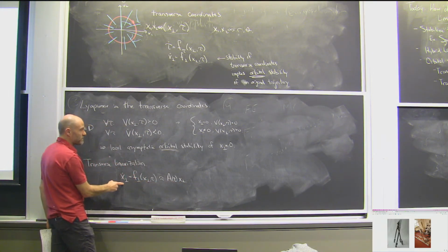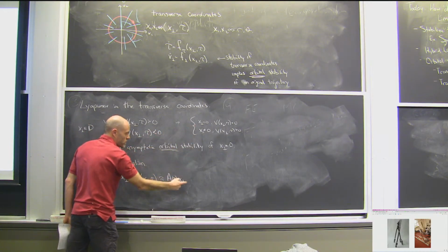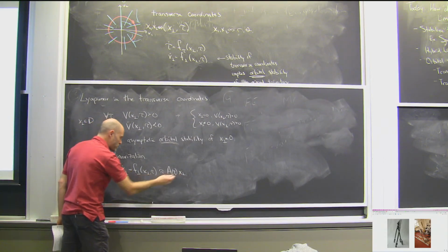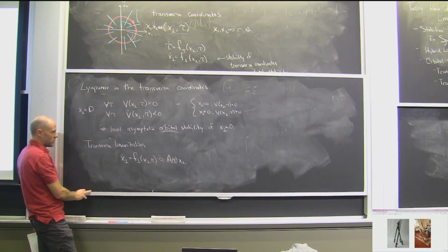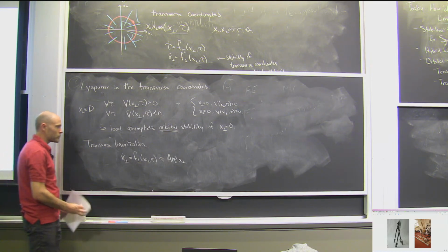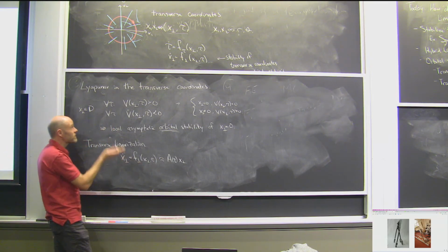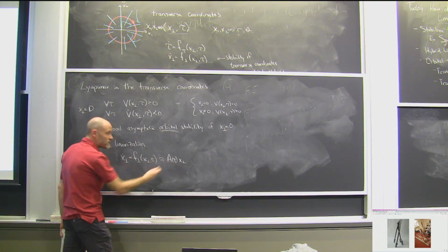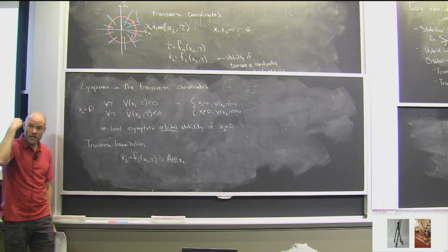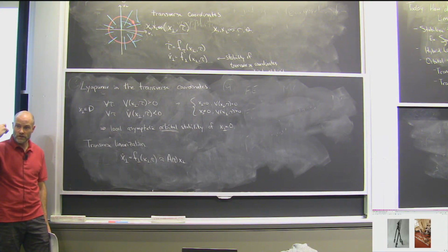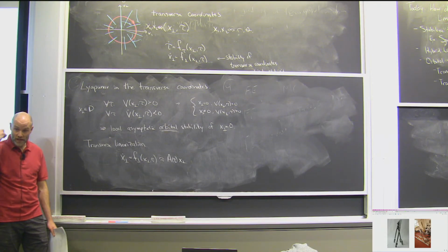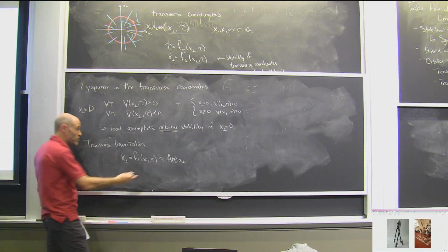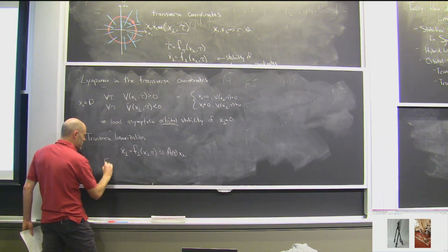Since x perp I've defined already to be at the origin, I'm not writing a bar this time. I'm saying x perp equals 0 is the origin, so it's my desired solution. So I can linearize the dynamics in that blue coordinate system, right? And I can use this, for instance, to find an initial Lyapunov candidate. Remember the way we found a Lyapunov equation? We solved the Lyapunov equation just to find a Lyapunov candidate to prove stability. I can now use this to find a Lyapunov candidate.